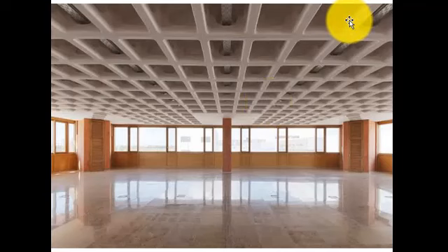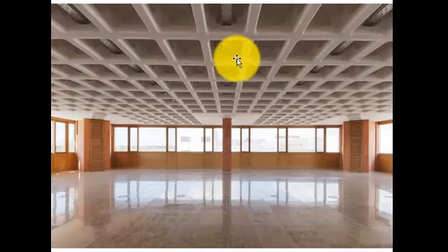So this is spanning in 2 directions. Look at it in 2-way. You have 1-way and 2-way. So this is spanning in 2-way. Why? Look at this rib. Look at the direction. It is going in X direction, going here. Also this going like that, also this going like that, and this too going like that. So that is the first direction. Then the second direction they are spanning. Look at another rib crossing it, it is crossing it here. So it is now giving it a 4-cornered shape. Another rib crossing it, you can see there. So it means it is spanning in 2 dimensions, in 2 ways.